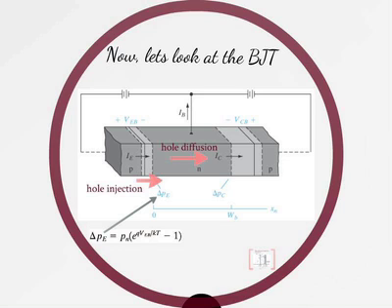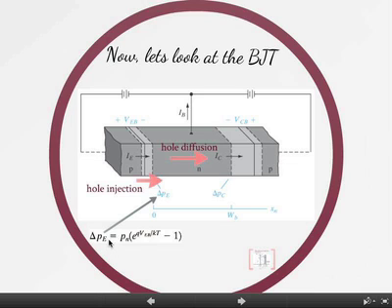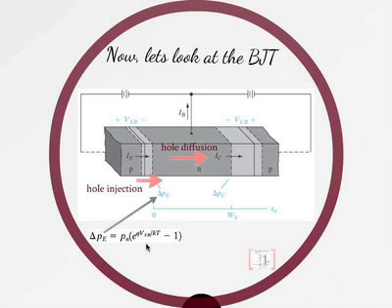As you move away from the interface, there is an exponential decrease because of recombination and diffusion. That was the solution to the diffusion equation. We already did this, so I'm not going to do it again. We know that right at the interface, the excess hole concentration should be given by an exponential dependent on the forward bias voltage, V_EB being the forward bias voltage, emitter-base.